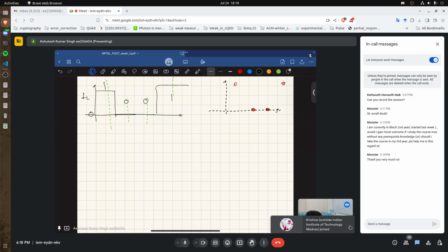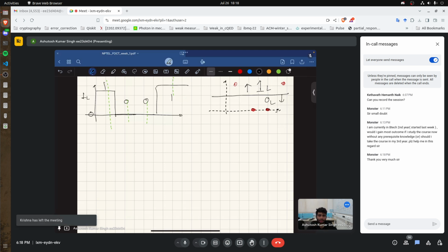And after this I just put a normal thresholding. Whatever is above this is my logic 1, whatever is below this is my logic 0. So you see that transmitting data in digital is fairly simple. We are very easily able to collect the data, which are bit 1s and bit 0s, just by this. This was one thing.